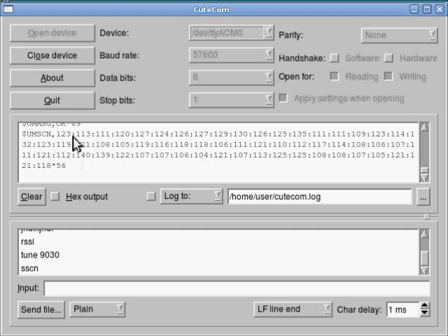This is useful if you want to see what the noise levels look like across the spectrum. Now this is a subset of the entire ISM band. This goes from 910 to 920 megahertz, but it gives a good feel for that section. It's useful for diagnostics, and that tends to be the part of the spectrum where most of the utility transmissions will be seen anyway. So we can see here that we have a couple channels where we have some reasonably higher signal levels. These are not problematic, but they're higher than the rest of the band.